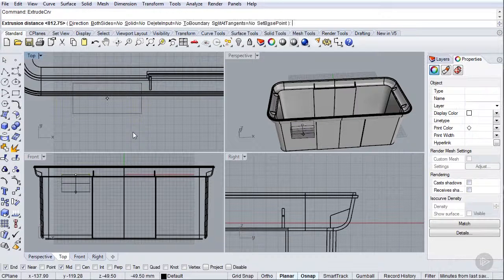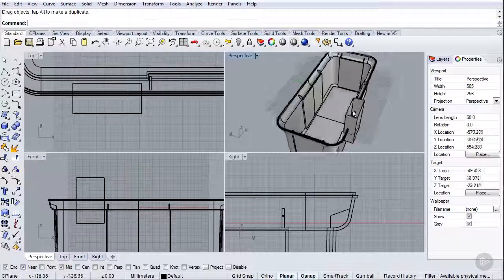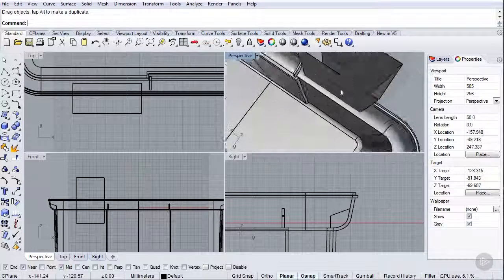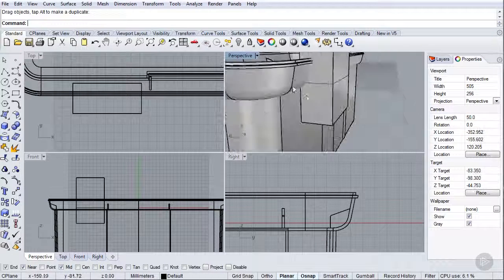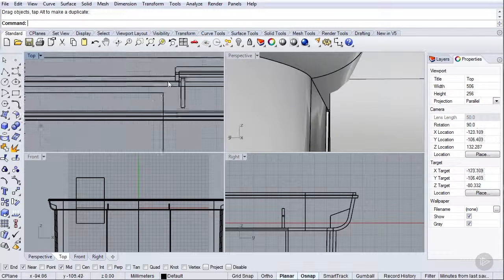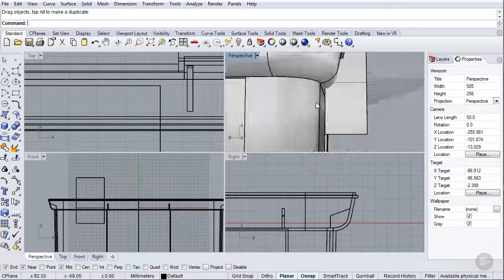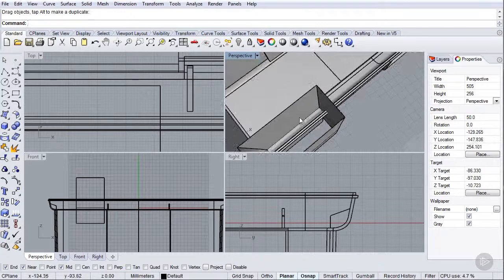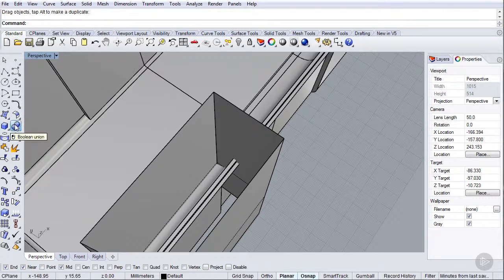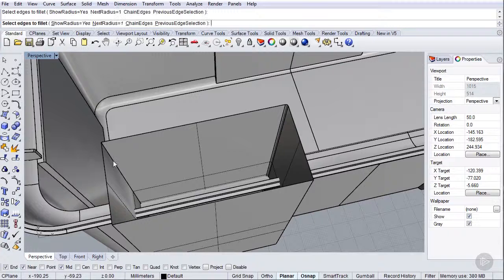Going to extrude this piece. And we're actually going to cut away a hole into this piece we made earlier on. And it's going to get quite close to that surface, but there's still going to be a little surface on the underside here. Okay, I think that works. I'm going to put a very small radius on this inside edge now. One here.